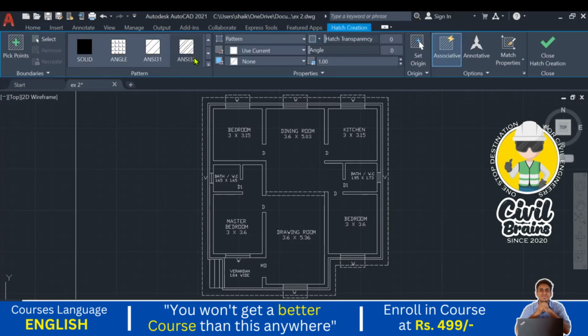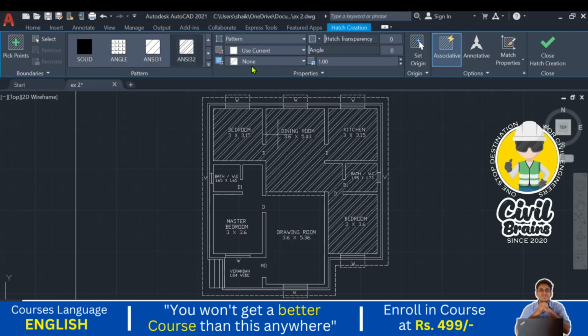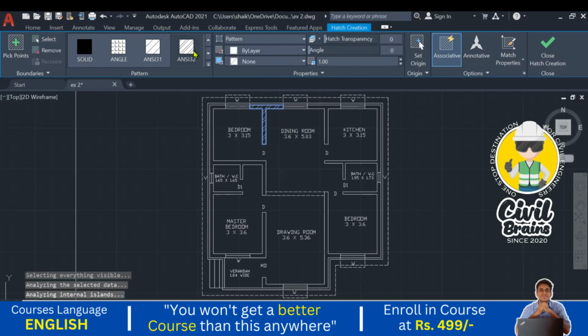Always remember, whether it's burnt brick masonry or stone masonry, or blocks or anything. If it is a concrete wall, then we need to show the concrete, but here concrete will not come. Here it is our burnt brick masonry. I just click on this one. This is our hatch. Always remember. Okay, and for the foundation, one straight line, one dash line, one straight line, one dash line, that is for the size stone masonry. I just go here, wherever the wall will be there, I just hatch this wall. Okay, so just click on this one and click on the points.